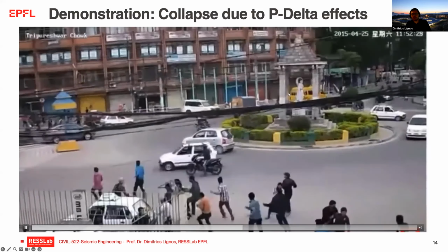And of course, if you are looking into buildings such as the one here, this is a 4-story building that was tested on a shake table several years ago, you see that because of the development of a first-story mechanism here, when I measure the moments that I anticipate because of lateral load, these moments are essentially amplified, and eventually the frame loses stability because I have also the formation of plastic hinging in this position and this position, and I have the development of a soft story mechanism here that essentially is not able to hold gravity because of large lateral deformations here.